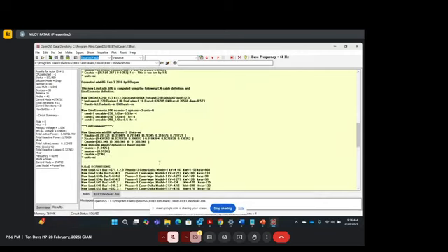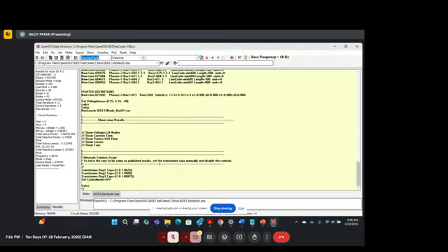Let us try that. There is this alternate solution script in OpenDSS. This is commented out, but we can force the taps in the regulators to be at a certain value. And then once we fix the taps, let's see if the power flow results match or not.